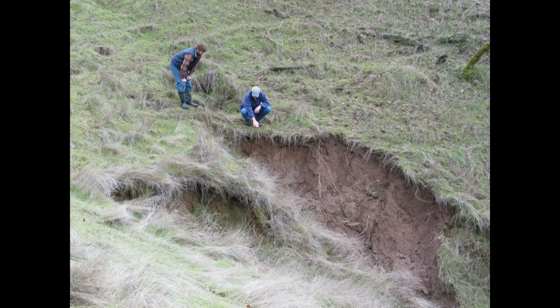Then moving on to larger scale landscape level erosion features. You'll be looking at whether there are gullies, slumps, or headcuts on your landscape along the hillsides or hill slopes. It is important to understand here that there could be underlying geological and soil reasons that might result in these conditions, as well as road drainage. So take note of where these features occur and take your time to note the relative contribution of landscape conditions and management, because this will help you in the next steps of your plan to prioritize projects and mitigation measures.